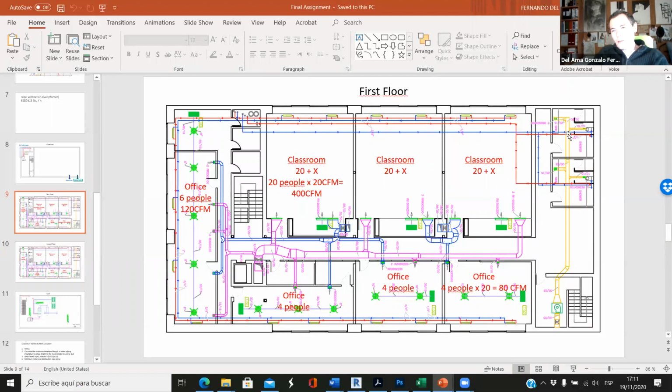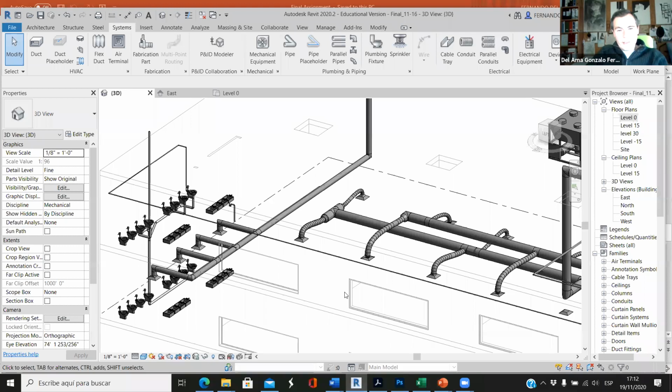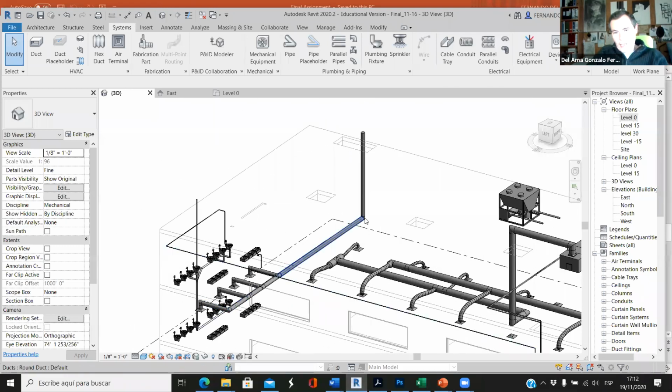Okay, so that's why we need to have this exhaust go all the way up. Having ducts going through windows is not an option. You will see this sometimes, but it's not legal first, and then it's disgusting. Because if we are getting rid of our exhaust air through the window, then the neighbor upstairs will end up receiving all that air that we are getting rid of. Okay, so don't do that. So make sure that this exhaust pipe goes all the way up beyond the roof level.